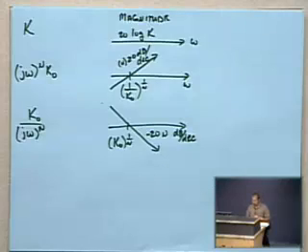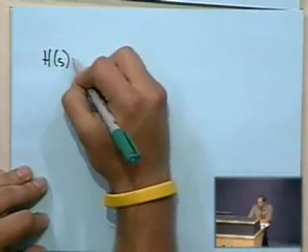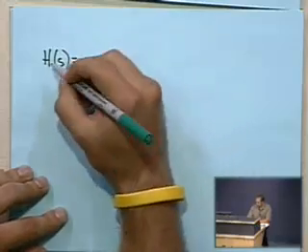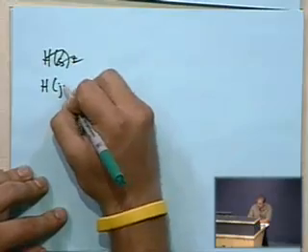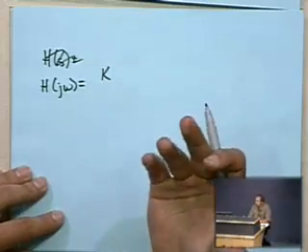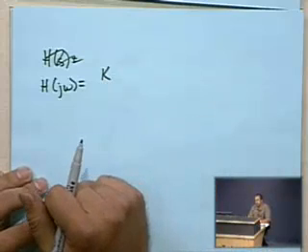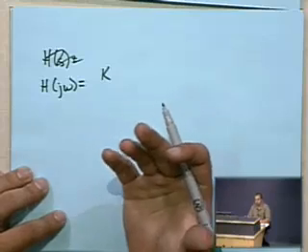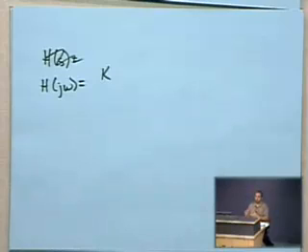Yeah. So, let's see, our standard form. We will have a transfer function of the form H of s, or H of j omega, let's just make this j omega instead. First you're going to have some constant k, and that could be a 1. There's nothing wrong with having a 1 there. In fact, that's fairly normal for something like a simple filter. If I want certain frequencies to get through, and other frequencies not to, and I don't necessarily want to amplify what I'm getting, I just want it to either come through or not, your k value very well might be a 0, or it might be a 1.